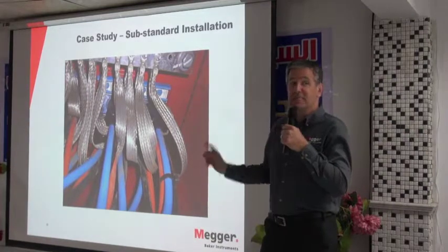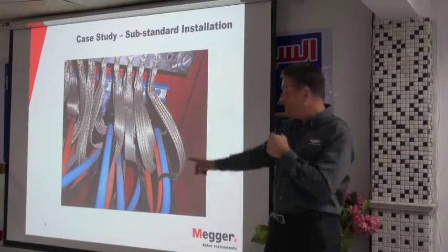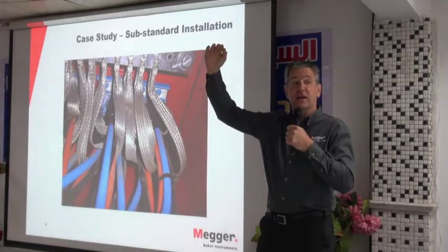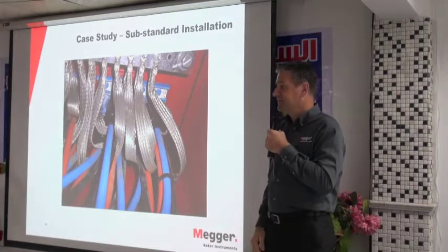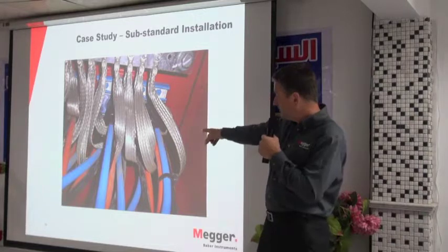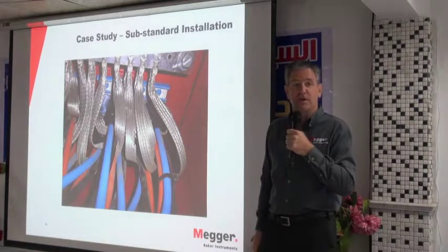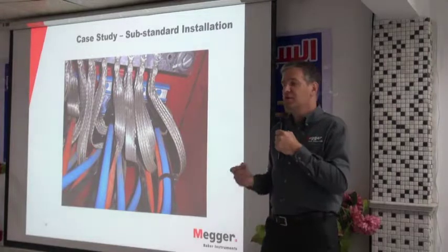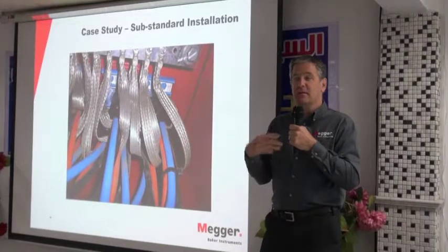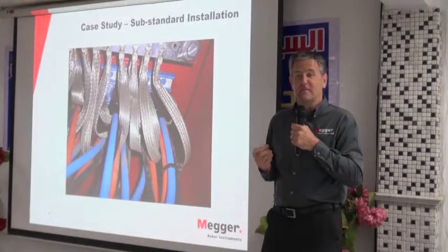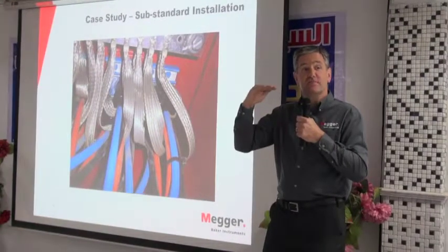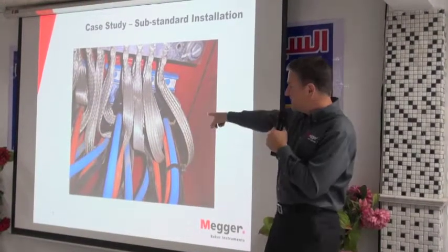And that ship was 18 months old only. So in 18 months, our megohm value has come down from 20 or 30, 40 gigohms to 26 megohms. And the standard says it's okay. But that motor, or that cable would have failed pretty quickly. So what I'm saying to you, although the standards give you values, sometimes you have to make better values than the standards for more reliability. If you want your motors to be reliable, you need to have a higher megohm value. And then you can see the problem coming.